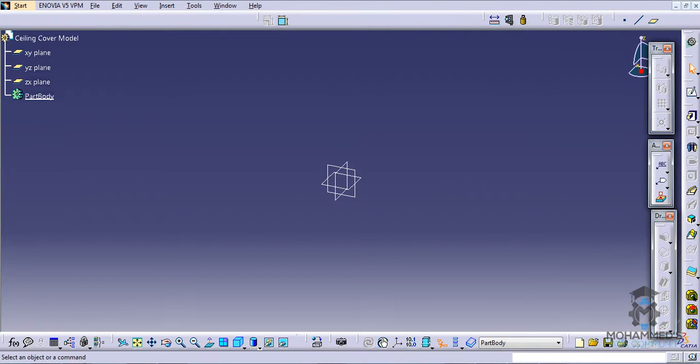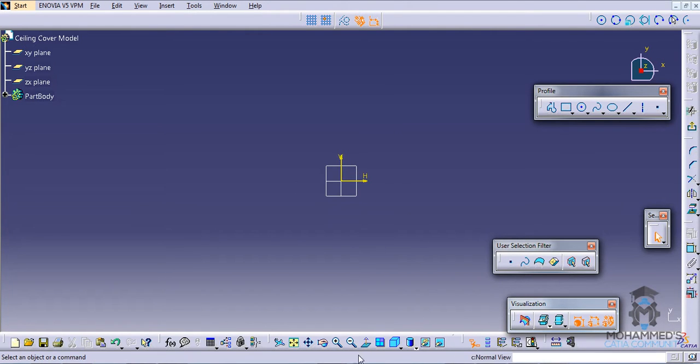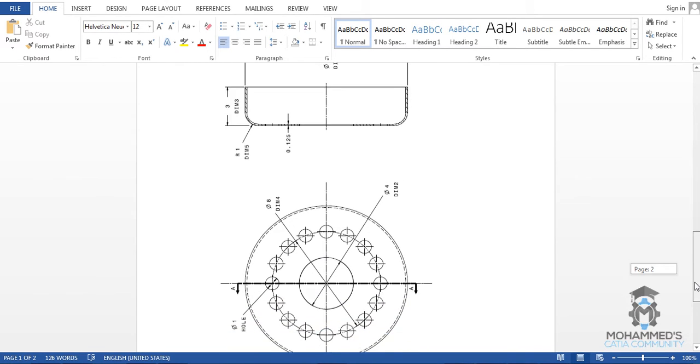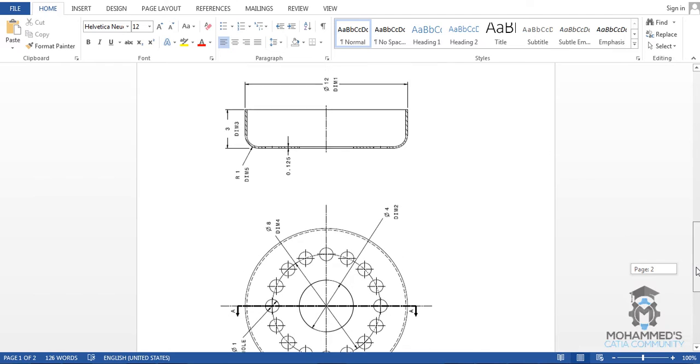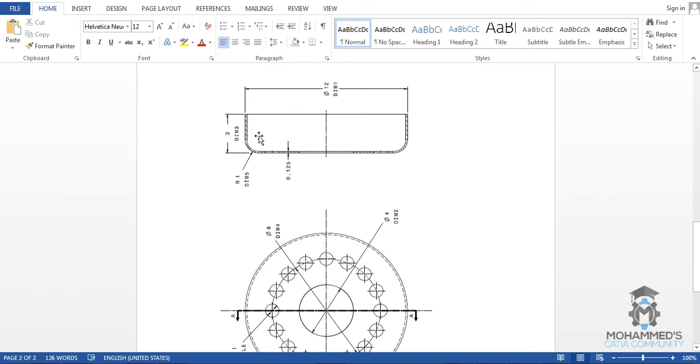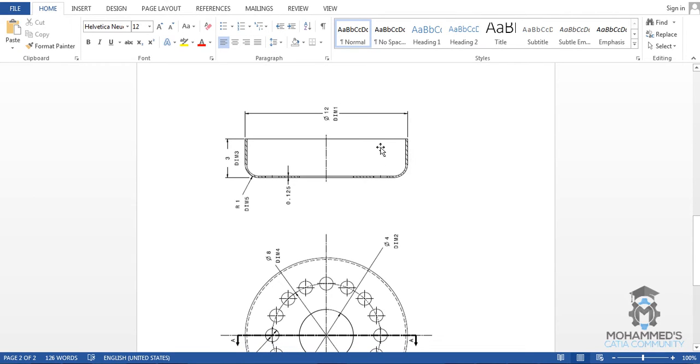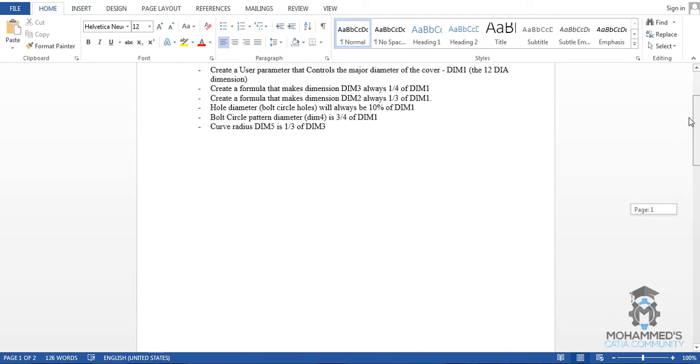model. Let's let the workbench open up, and then let's start creating a sketch on the XY plane, and let's look at the drawing. So firstly we just have to go through any drawing that we get, and as you can see it's just a simple model with the side and the top view. So we basically have 1, 2 and 3 concentric circles, and then it's been padded and then shelled and then given some dimensions, so it's pretty easy job.